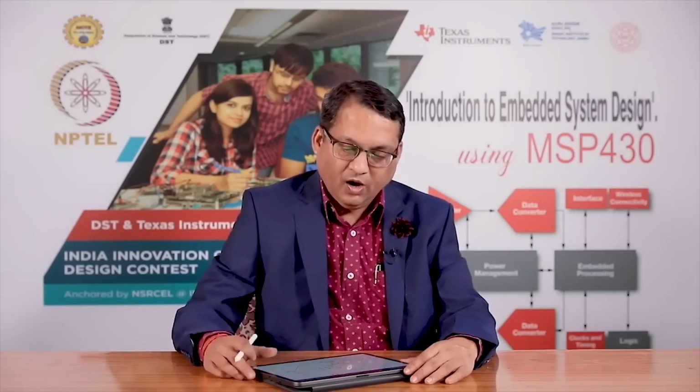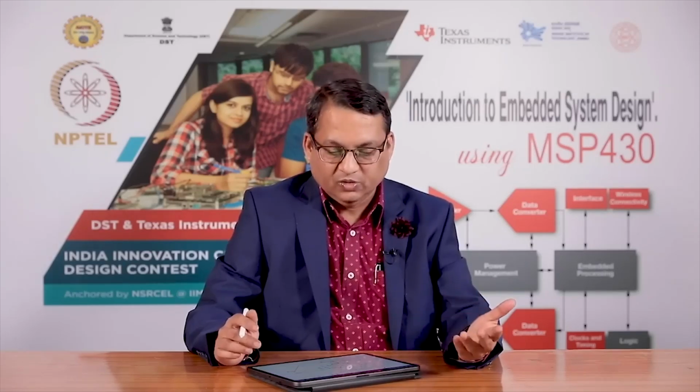How to achieve that in real life, in practice, we would consider when we are looking at system design issues, where we will show how to design a PCB from a schematic. What do you do to ensure that there are two parallel tracks, one for providing power supply to the analog voltage and the other to supply voltage to the digital part of the circuit. We will consider that, but this is an important point to keep in mind in case your microcontroller has separate pins for analog and digital subsystems within your microcontroller, that you design the routing, you design the PCB appropriately so as to do justice to the internal components.